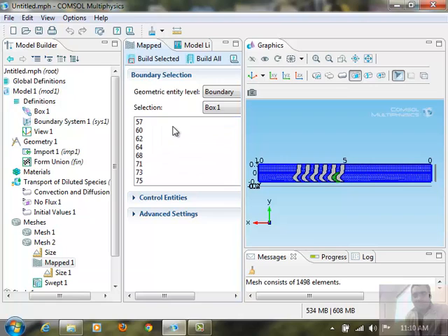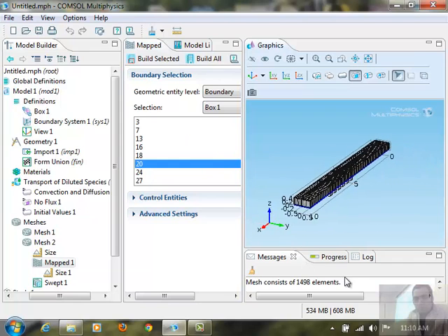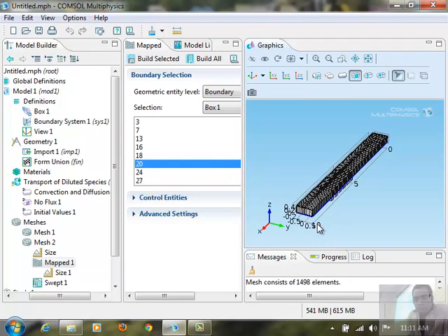The main message I want to convey is, even if it is a complicated geometry but an extruded geometry, then we can use mapped mesh, and you can control and make it more uniform. So we have generated the sweep mesh for the mapped mesh for the rectangular domain. Similarly, you can generate for these grooves here again.